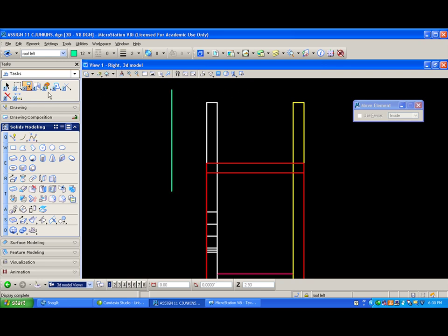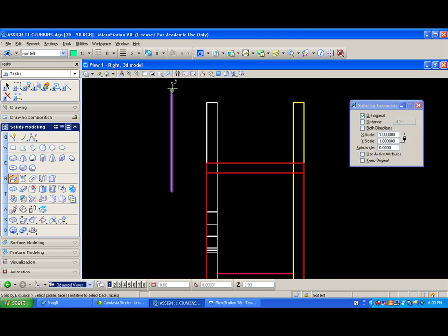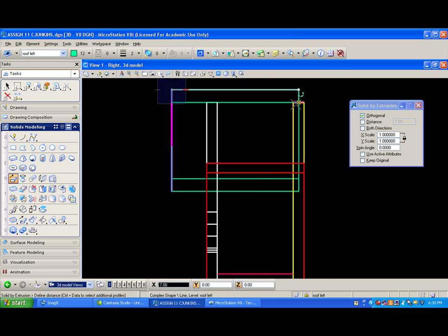And what we're going to do is just extrude this, grab it right by the top. We'll hit F for front, or S for side, pull it down, hit enter, and I want a 1 inch overhang on the back, so I tentative point, hit O, and then moved it 1 inch. Well, tried to move it 1 inch. There we go, 1 inch.